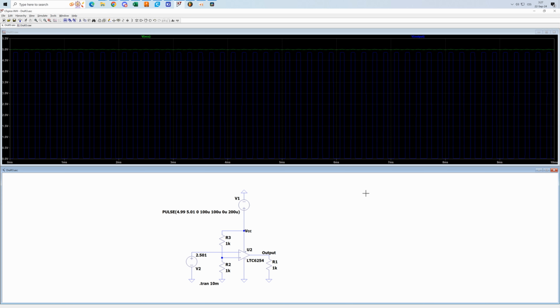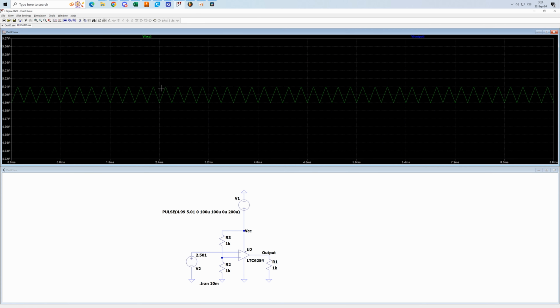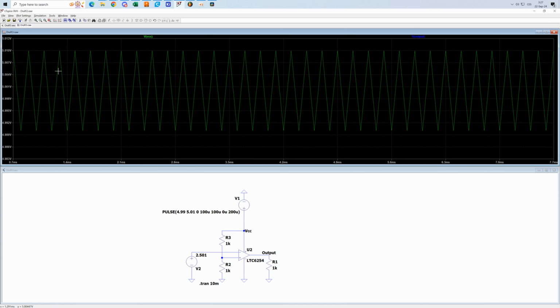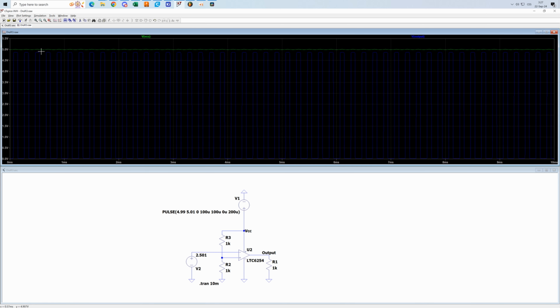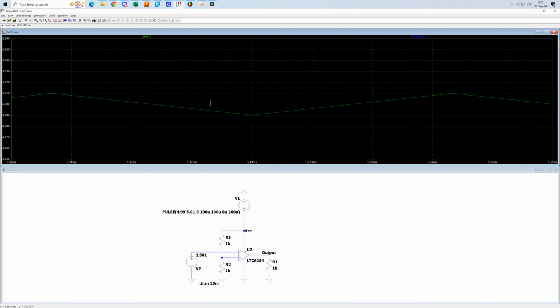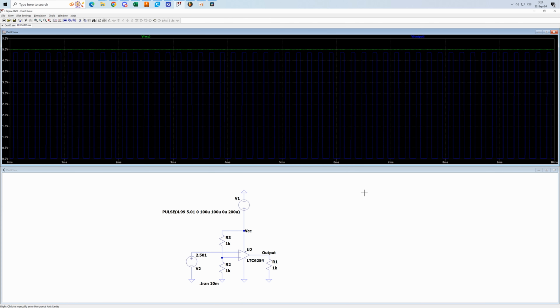So why is that the case? Well, it's because when I said that we have nice 5 volts on the supply rail here, I actually lied, because if we have a closer look at the supply voltage, we can see it's not actually that nice. It's not nice at all. We have this sort of voltage ripple. So on a large scale, it may look like the 5 volts is nice and stable, but if you zoom closer, well, we can see that it is not as good.